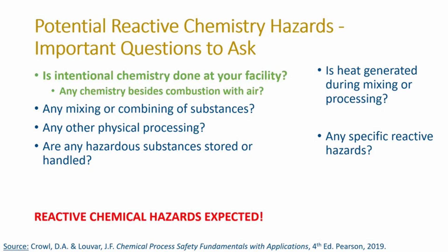A first situation where we expect there to be reactive chemical hazards at the facility is if we could answer yes to the question of, is intentional chemistry done at the facility? And also yes to the follow-up question of any chemistry besides combustion with air being carried out at the facility. Now, combustion is also a special reactive hazard, and it's not the focus here as it's handled by separate codes and standards.